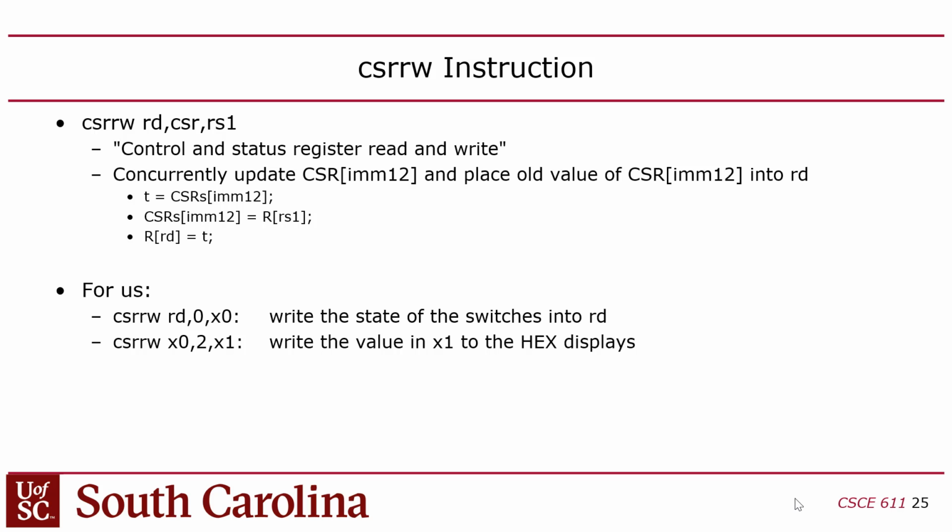The problem is we don't want to do that in this lab. We just want to have a separately defined behavior for the LEDs and the hex displays. If you apply this instruction on the hex displays, it's output only, because you can't read the hex displays. I mean, I guess you could read whatever was last written, but we're just treating the hex displays as write only. And the switches are read only. You can't write the switches unless you had an actuator on the board that would flip them without you touching them, which we don't have.